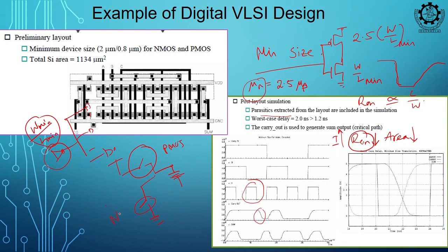If this is made up of NMOS and this is on, my output is connected to the ground, right. So, my transistor is just behaving like a switch, nothing else. If it is a switch, what is the model of a switch? Switch will have some on resistance, right. Ideally this switch should have 0 resistance, clear. The job of a switch is to connect, no drop should be there.